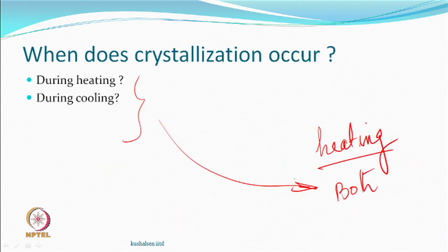So, it happens during heating, it happens during cooling, rates may be different, and then we can get a textured yarn. So, that is the crystallization part of it, which is important. Randomness and disorientation will happen, but a good amount of stability, that we say dimensional stability, recovery from deformation, all those are going to be more governed by how much crystallization we have done.